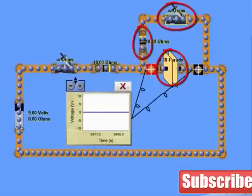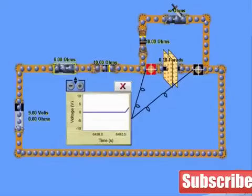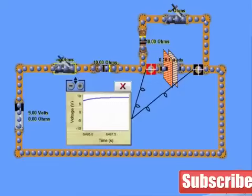If we close the switch on the lower loop, the charging loop, we'll be able to see on the voltmeter how the capacitor charges. Let's give that a try. We see the voltage rising to the final value, which would be the same as the 9-volt battery. If we remove the battery from the circuit, we see as before, the capacitor holds the charge, remains at 9 volts.